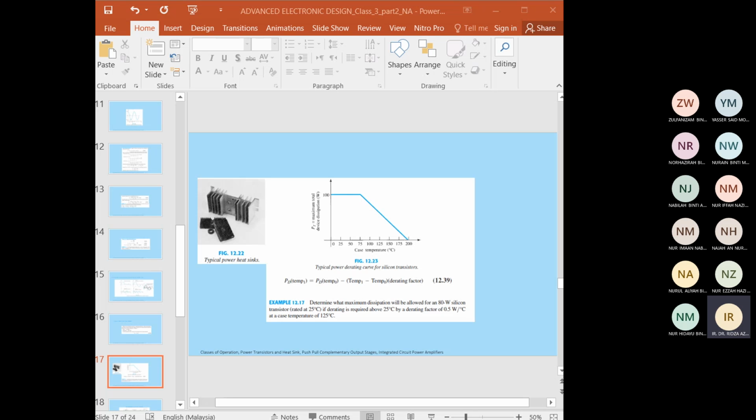So sometimes even with the infinite heat sink, or if we do not use the heat sink, the case temperature is held at the ambient air temperature. The junction will be heated above the case temperature and maximum power rating should be considered.